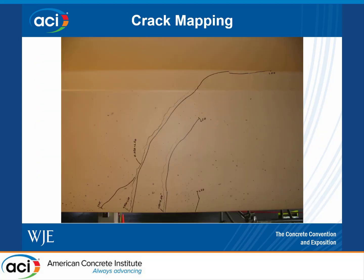This is a photo of the crack mapping that we performed prior to the start of the test. It takes a decent amount of time to do this. You want to thoroughly map out all the cracks, record the initial crack locations, lengths, and widths on the member prior to applying any load. We often use a different color to map the cracks during the subsequent load stages, so it's very readily apparent what was the initial crack and what was the propagation of the crack during the testing.